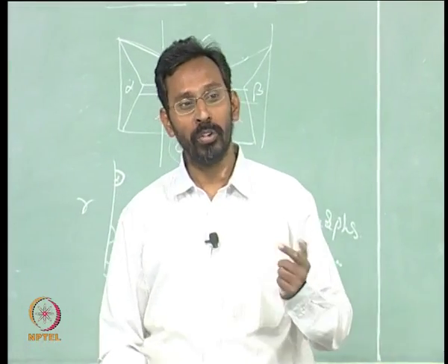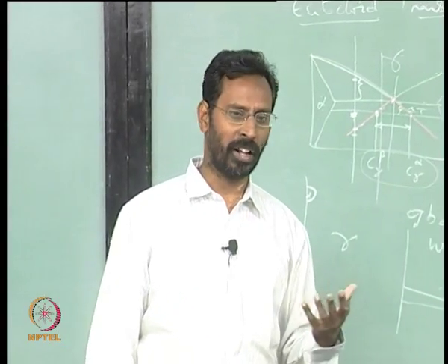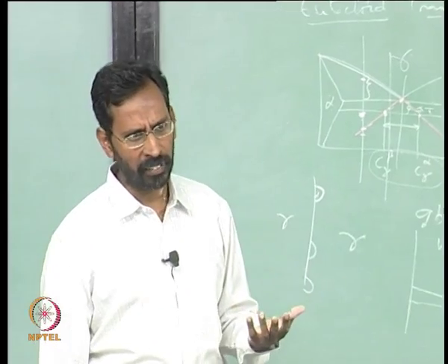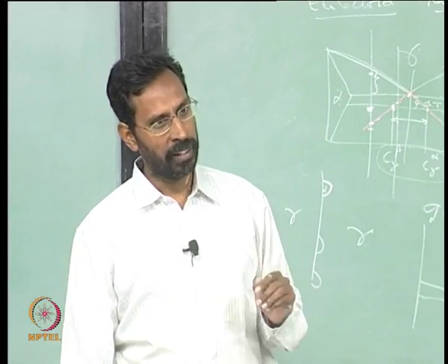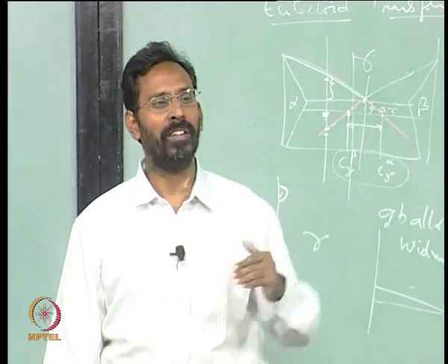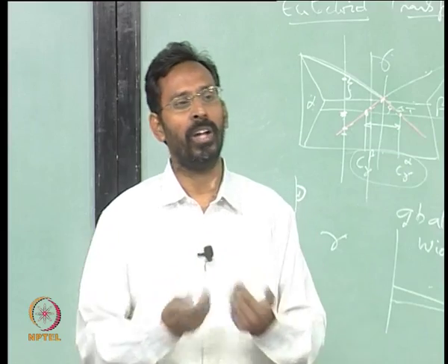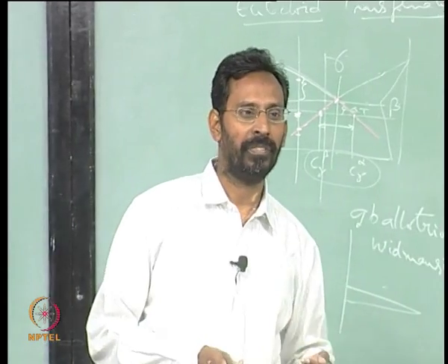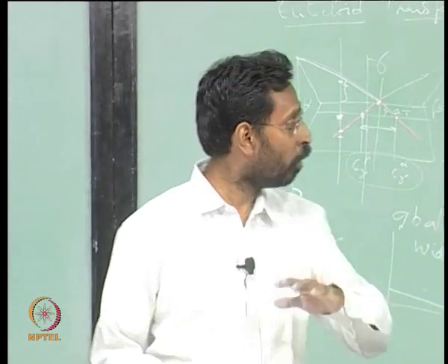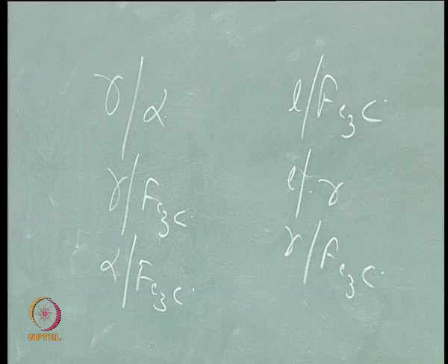Okay. In aluminum copper, two solid interfacial energies are lower, basically because one is a theta phase, which is actually, in fact, theta is not even orthorhombic, it is BCT, tetragonal, sorry, orthorhombic is Fe3C, and alpha is cubic. But if you look at high temperatures, the interfacial energies of both of them are close to each other, and as a result they can come out together. A tetragonal structure has correlation with a cubic structure, excepting the C axis, everything else is similar.